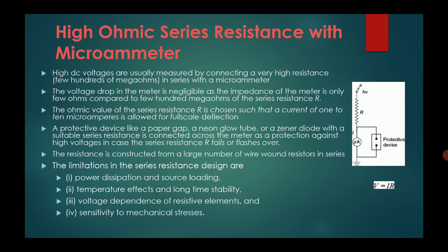Then there is the temperature effect and long time stability. The temperature will rise and the stability might be compromised if you connect it for a long period of time. Then there is voltage dependence of the resistive element. So this resistive element is dependent on the voltage, so depending on the range of voltage we are going to measure, we have to choose the resistance R so that we have a deflection between 1 and 10 microamperes.